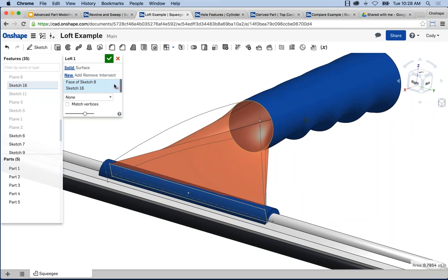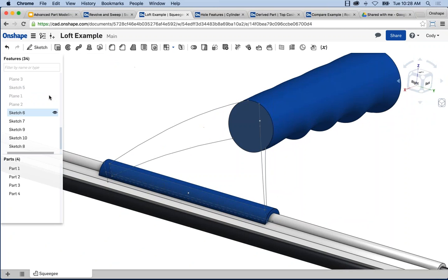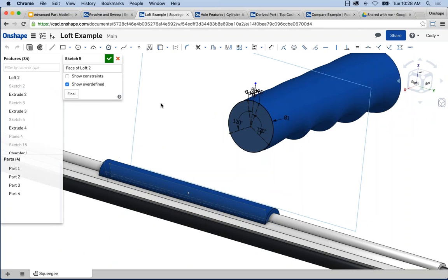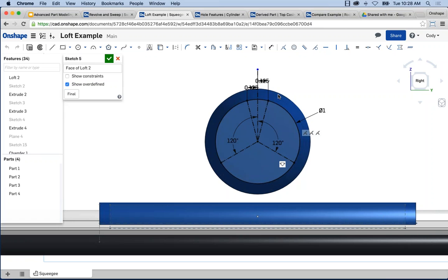So what you can do is instead use a sketch. Let me show you what I mean. This is sketch 5. And just a tip is it's still a circle. It's just a sketched circle, but it's been split into 4 pieces. And that's the key difference because now it has 4 points, just like a rectangle. And the neat thing about this is now when you loft between this sketch and the rectangle, you'll get the correct orientation. The correct points will map to each other and give you a much smoother transition.